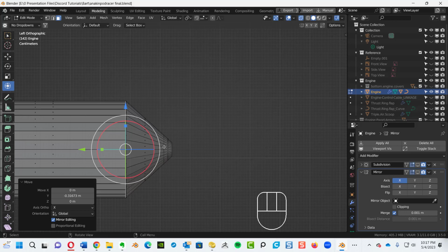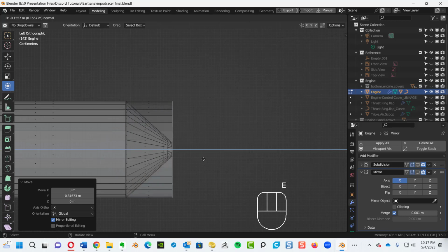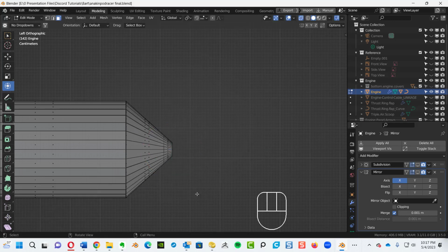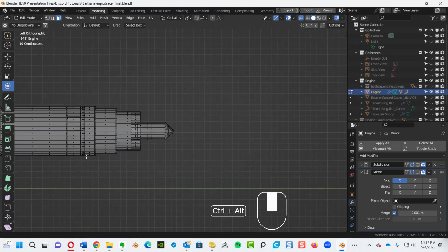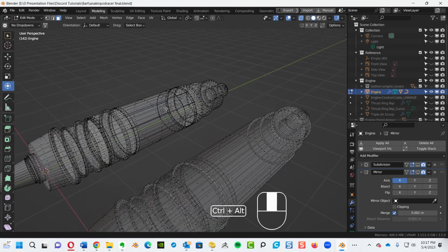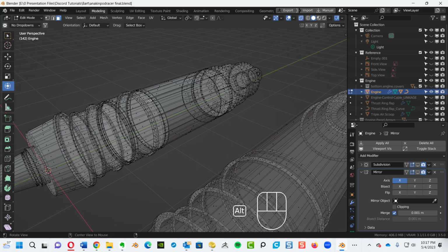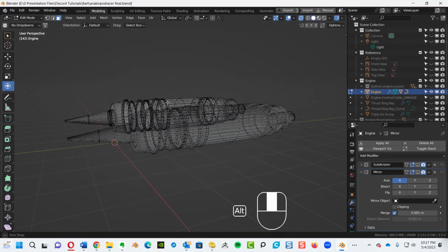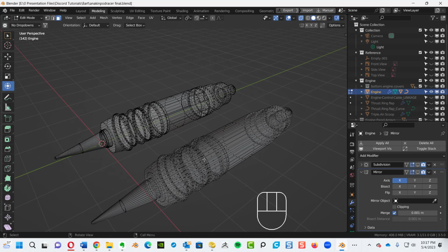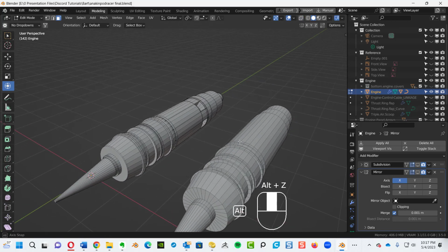And let's go ahead and give this an extrusion. Guess we could have beveled this too, but it might be easier. Just go give an extrusion here, and then hit the S key and pull it on down. There, done. All right, there we go. So there's a piece. All right, now why am I doing this? I looked at yours, and you've got a whole bunch of individual little rings that you just duplicated and you threw in there, right? To try to mimic the texture, and probably less time you could have done it this way, where it's all airtight as one complete piece.